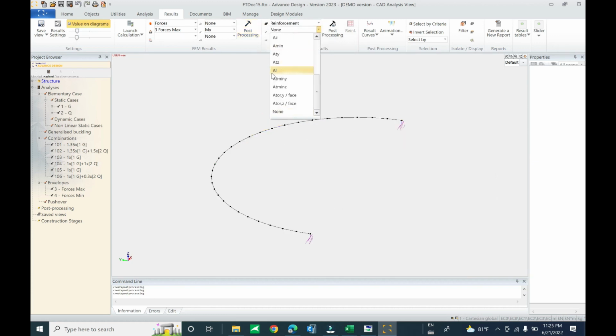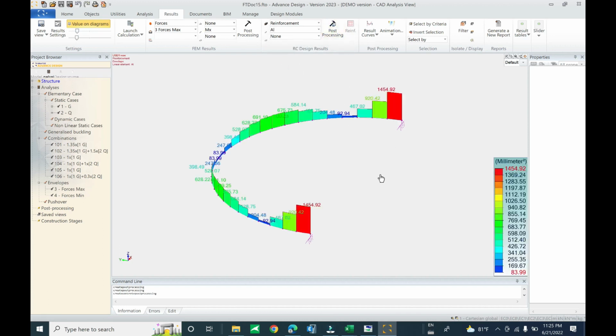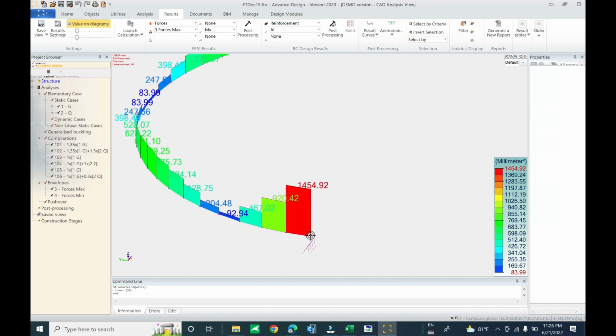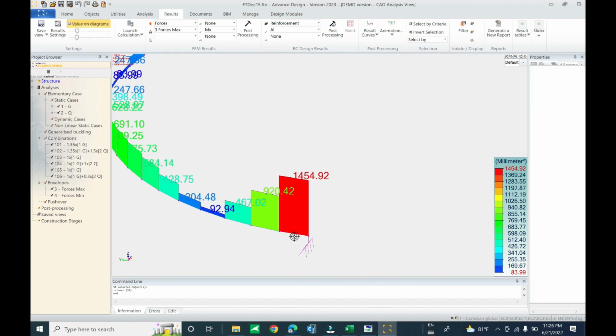Click on the AL, the torsion rebar. Click the torsion rebar, maximum at the support is 14.53 square centimeter. For this section, you can select and check this section is 40 multiplied with 100 centimeter, or the cross section area, the cross section rectangular.